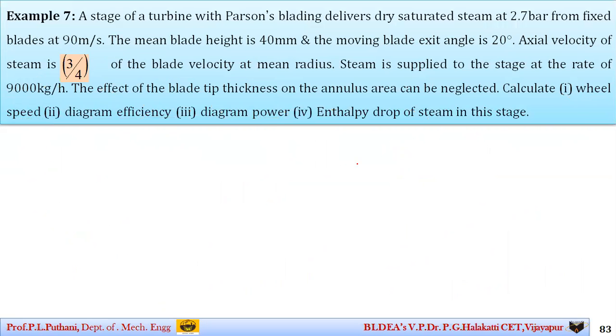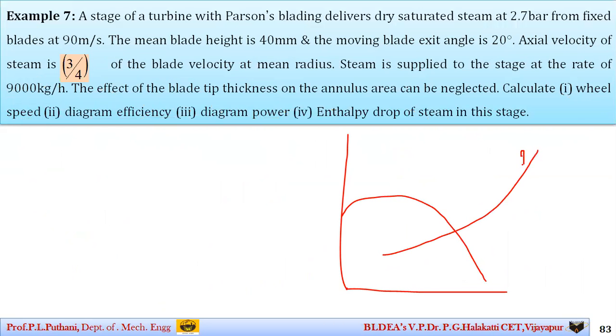An important point is there, students, when you go for the plotting of points here in the Mollier chart, this is your saturation curve. You have a pressure line of 2 bar and a pressure line of 3 bar. You don't have 2.7. So with the help of a pencil, you should see the spacing between these two pressure lines, and you have to draw a slight light line which takes the trend of nearly 3 bar. So somewhere you will get it like this. Here at the saturation curve where it meets, we call it dry saturated. This is the value of H1. This is point number 1.